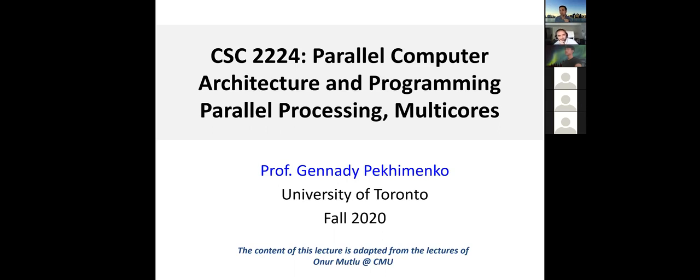You want to overlap these misses so they don't happen sequentially but in parallel. Okay, I see. You can read the papers for more, but it's a speculative technique that essentially uses the existing parallelism in the hardware and exploits the memory bandwidth available that's usually underutilized.